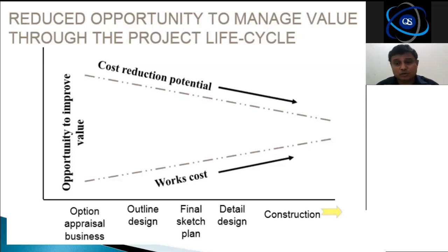And you know that about 13.5 blocks are required to cover 1 square meter. But this particular autoclave aerated block is twice the size of a normal block. So you need about 6 blocks to cover 1 square meter. So all these things blended together, you will feel these autoclave aerated blocks are good.